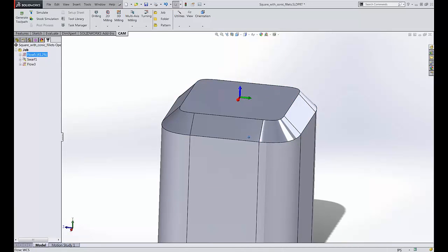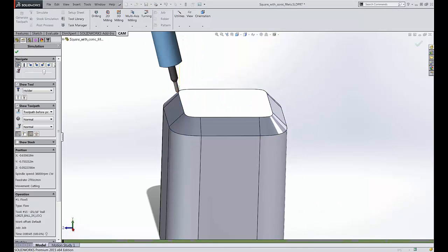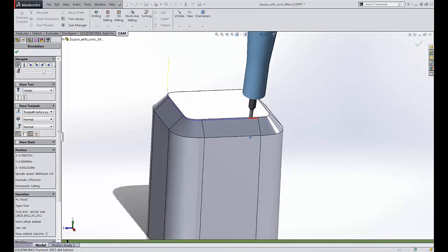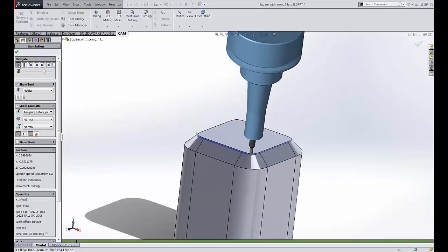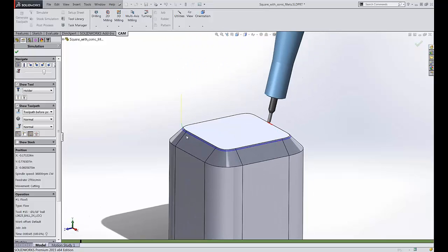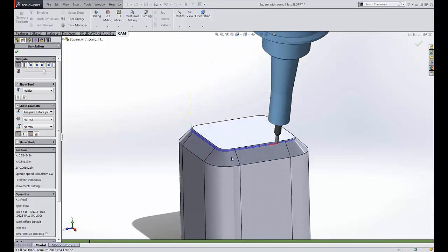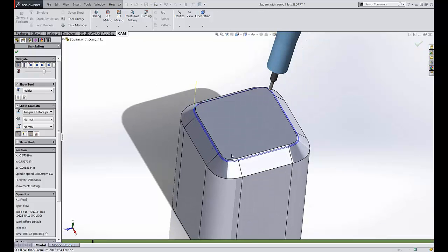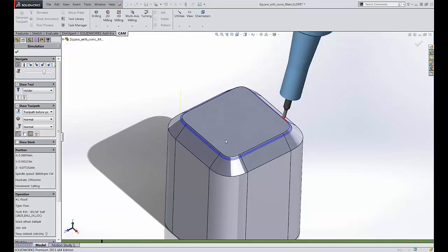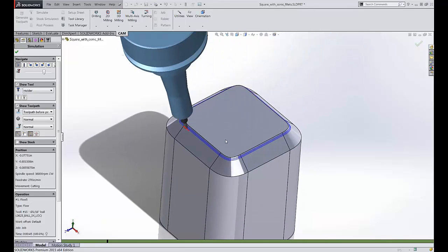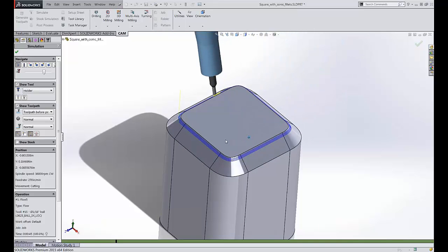All right, so we've reduced the amount of tilt that's allowed. And now we'll start to get some actual 5-axis tilting going on here. Right, you can see that it's maintaining normal to the surface. Flow is a toolpath that follows the UV vectors of the tool. That's important when we start talking about occlusion. Most of the other toolpaths in here are projection-based, which means that they can only project toolpath as seen from the Z-normal. Some of them have some undercutting support, but that's the basic gist of it.